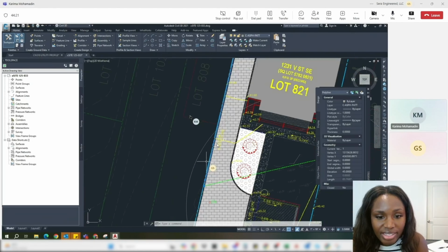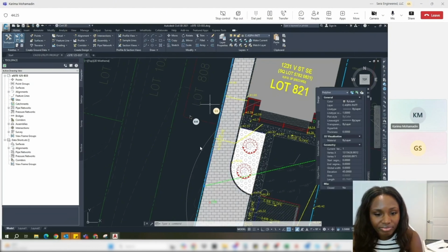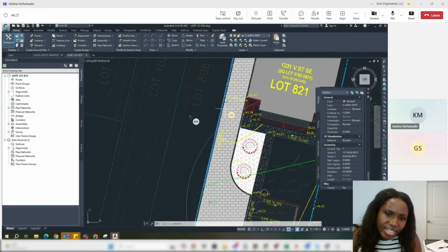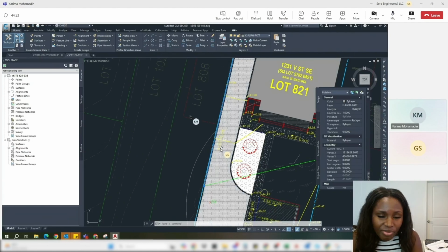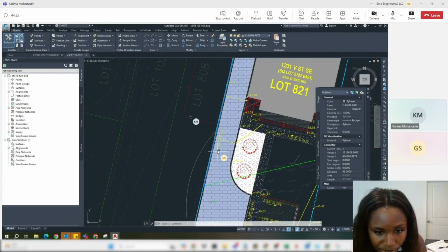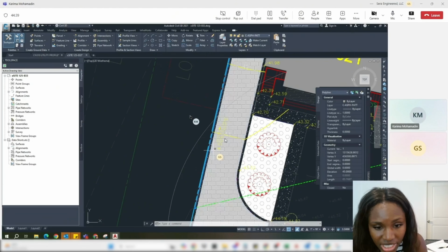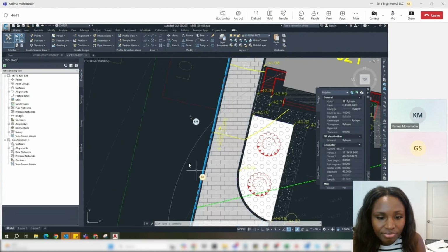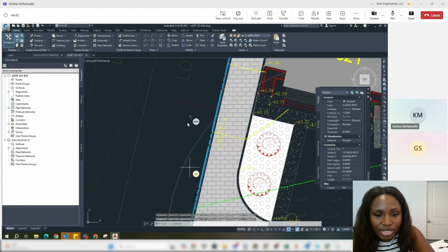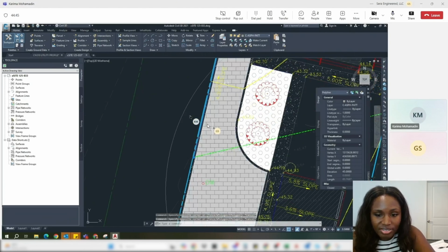So that's what an infiltration trench is. And so all this would be pavement, and water's going into it. That's one option. And the second option is to have a small wall here, so that this elevation can remain, so this can remain as permeable pavement, and not many changes have to be made along here.